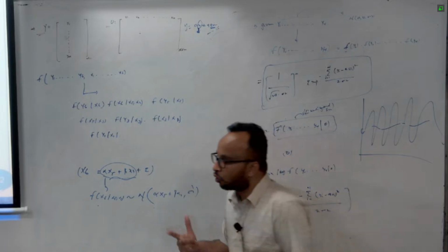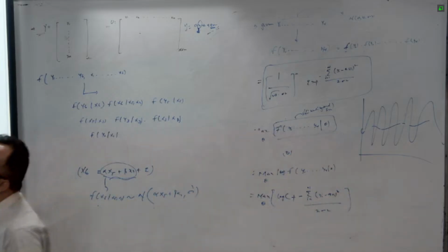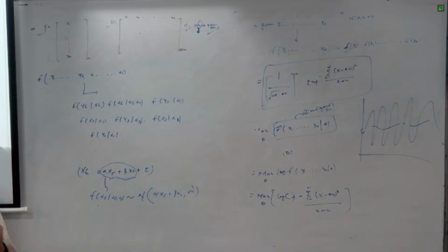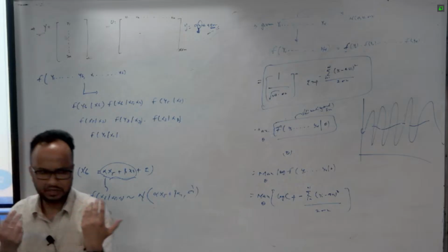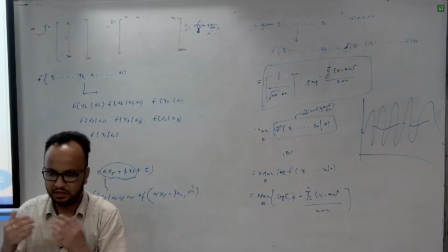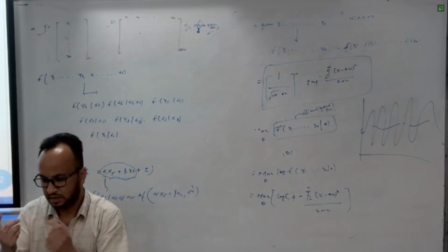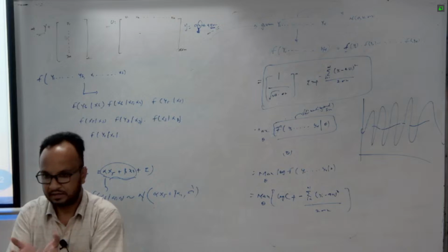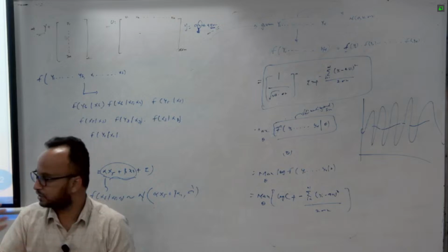And there is something called local modeling. I'm not interested in coming up with a bigger model. Can I come up with local models? Around that particular point which I'm interested in, I'll only consider developing a local model, predict, discard, then go to a new point, search the nearest neighboring points. I use k-NN search, nearest neighboring search algorithms, get the nearest neighboring points, and build a model. That's called local modeling.